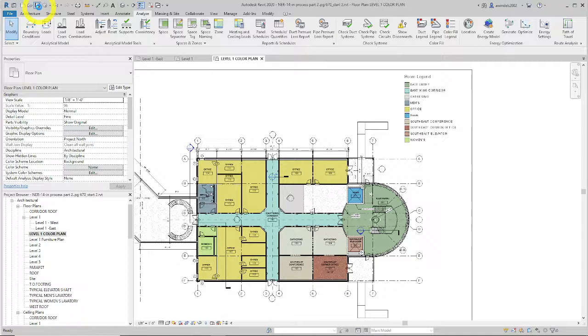We've gone a ways into this chapter. So we're going to move on to page 681, and we're going to add our first room separator. There's two ways to do this. You can physically draw a room without any walls, like in kind of a sketch mode, draw every one of them, or you can draw a line in the sand between the rooms and then edit it, which we're about to do. We're going to draw a line right here. So that's two different ways.